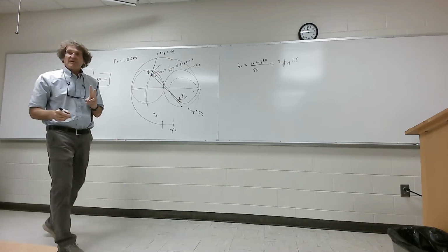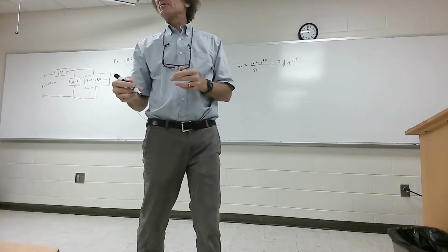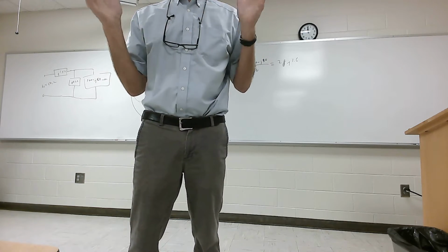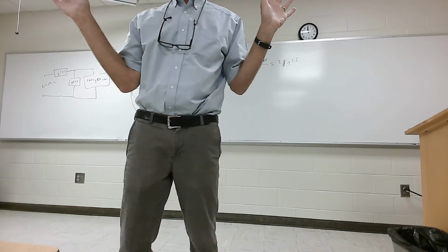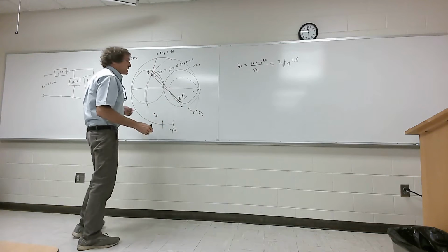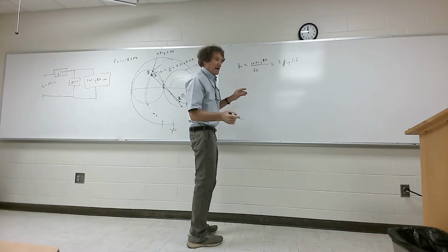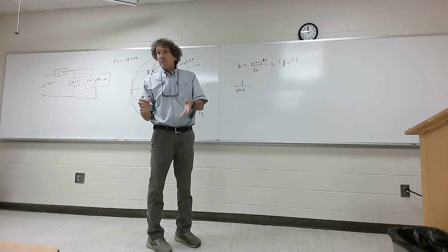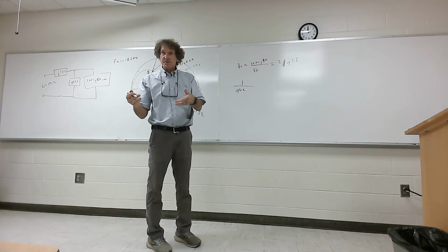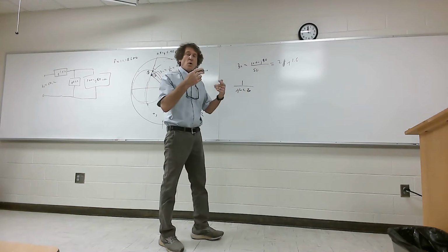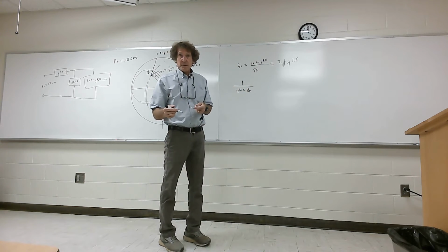Those are two elements. Now we have to get the values. I always recommend you start with impedances of the elements and then normalize them, then get the normalized admittance. That's just me, because you won't make mistakes that way. So for this one, this is an admittance, and so I know it's going to be a capacitor. I start with the capacitor. Capacitive reactance is 1 over J omega C. Then I normalize it, divide by Z naught, that's what normalization means. Now that's the normalized impedance, 1 over that is the normalized admittance. Do y'all agree with me?